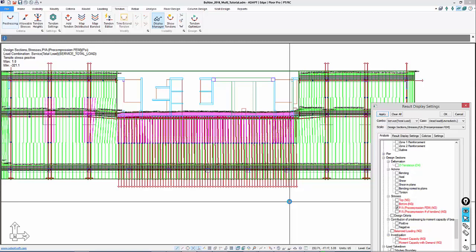So if you have fixed supports, if you have fixity between walls and slabs, this can affect the in-plane ability for the slab to shorten in plane in reality in the direction of the tendons. And whether or not that actually mimics real life conditions based on your detailing depends on the outcome that was produced.